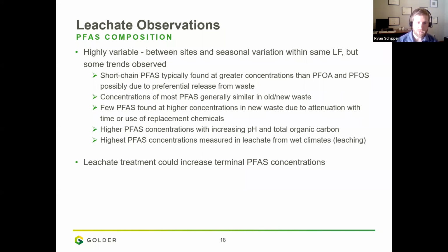So again, as I mentioned briefly before, if we do treat that leachate and we're not specifically looking at PFAS, so if we're using maybe a biological process that isn't effective for PFAS, we can actually be converting some of those precursors, which are longer chains, into these terminal PFAS constituents, which is what we're a little bit more concerned with. So that's another big consideration here.